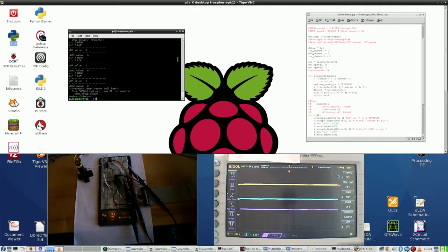So far not really lucky on getting some data, and this is a problem in itself, because if I go to menu it says SPI, well that's correct, and then there is a clock, channel 1, data, master output, slave input, or in this case master input, slave output, and select, slave select, device select, and that is high.